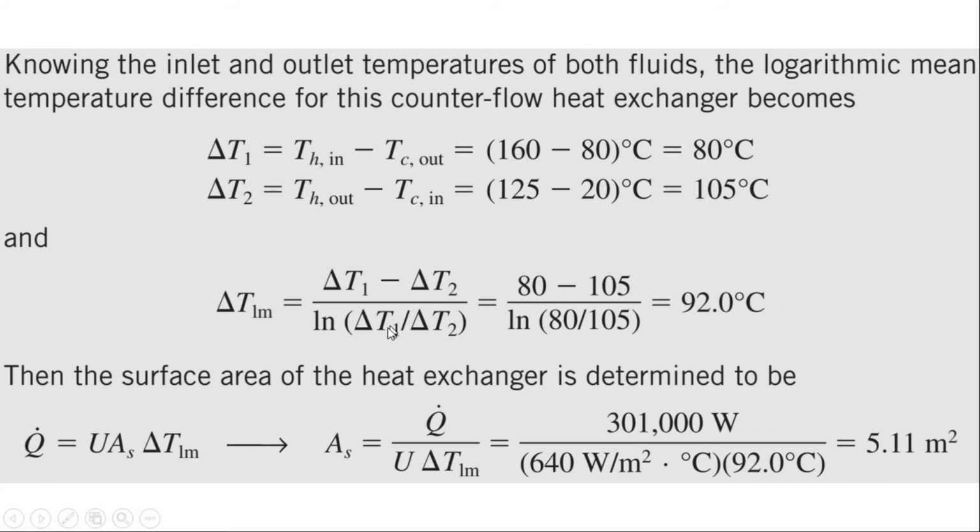The formula is given, and you can memorize this formula either for the counter current flow or the parallel flow. After putting that in, this is the LMTD, or log mean temperature difference, which is simply the average temperature, and after having this value you will put it in this formula.